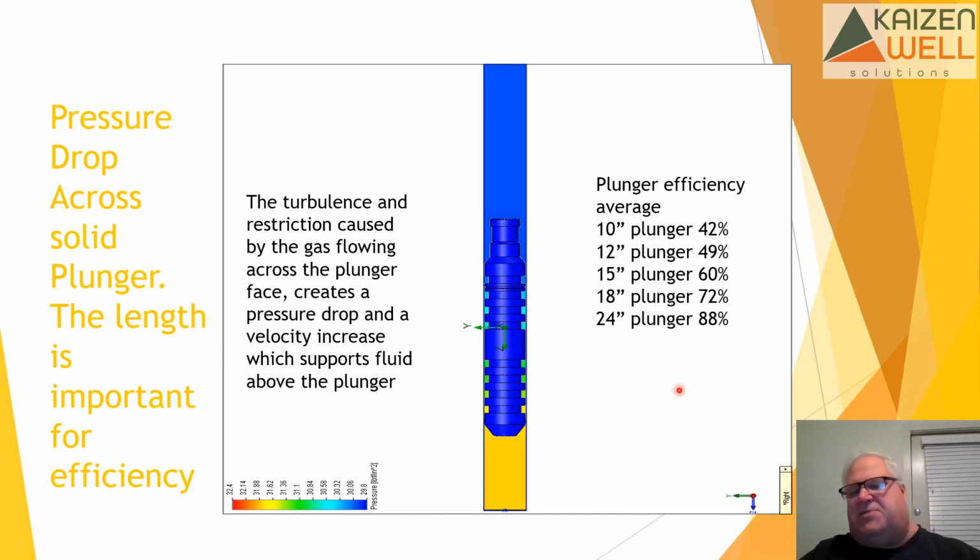A 90-inch plunger with two 24-inch seals is quite heavy. You'd think that thing would fall like crazy, but it just wouldn't. So it really has a big impact. For those of you working out there with wells where you've got paraffins and the wells are getting weaker, don't fall for the cheap little 10-inch plunger because you can get that for nothing. If you're having trouble getting that plunger into the wellhead, or cycling, or running properly, you want to start extending the length of that plunger.